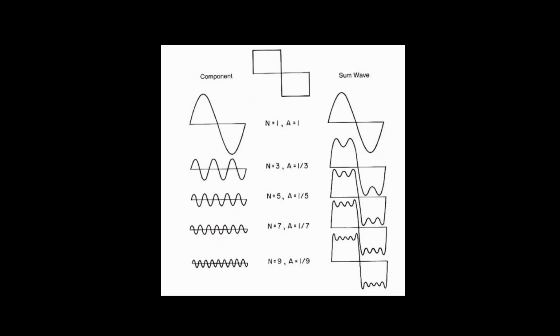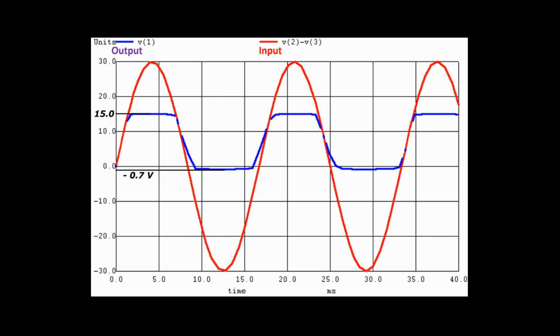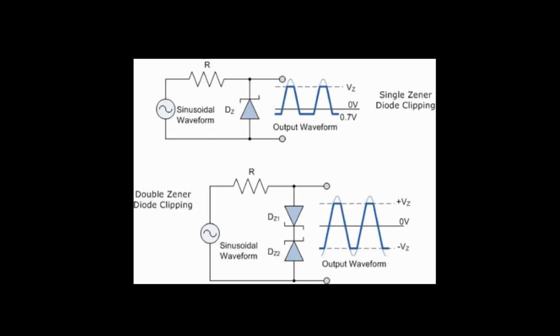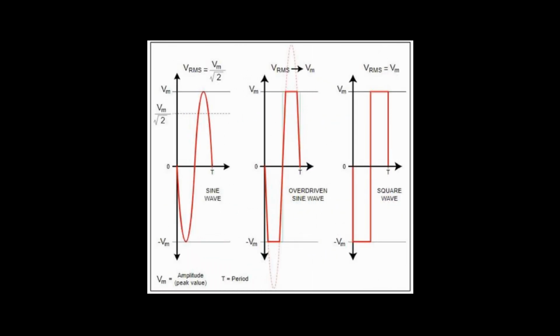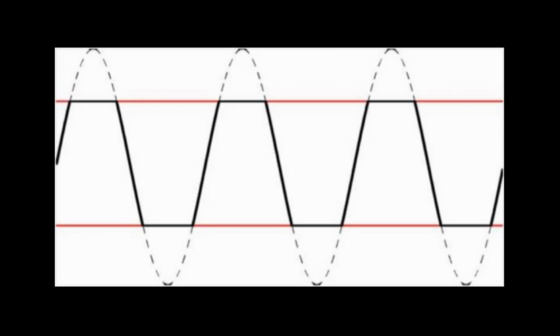So, some ways to cheat the system. Have you ever heard of a clipped sine wave? A clipped sine wave is kind of like a square wave. You can see how it reduces the time, because it clips off the top and you don't have all of that time to get to the very top of the sine wave. Another way to improve the situation is overdriving. If we, instead of the level 7 mixer, put in maybe 10 dBm or 12 dBm, that's going to get the diodes into saturation faster because you're not using all the sine wave to get them there.